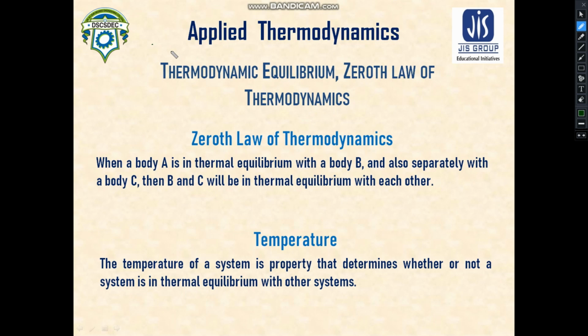Okay, so this is the condition when thermal equilibrium is reached. Okay, so we can define thermal equilibrium as the equilibrium states achieved by two or more systems, which is obviously characterized by restricted values of the thermodynamic properties of the systems after they have been in communication with each other through a diathermic wall.